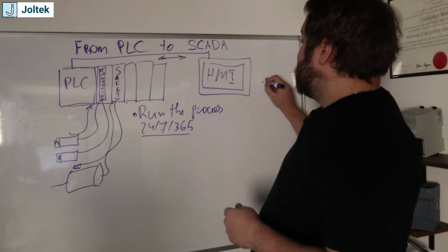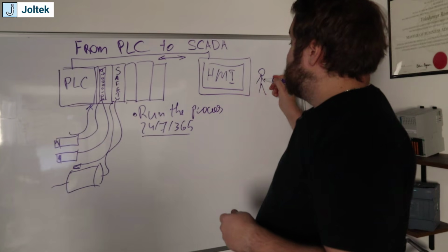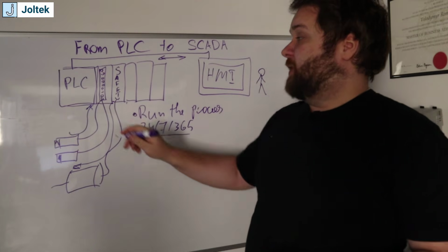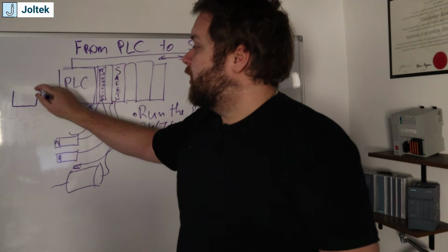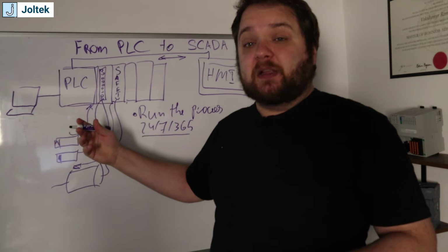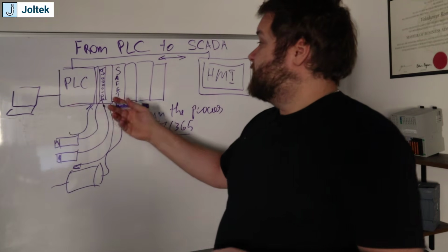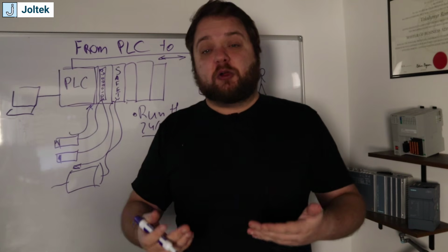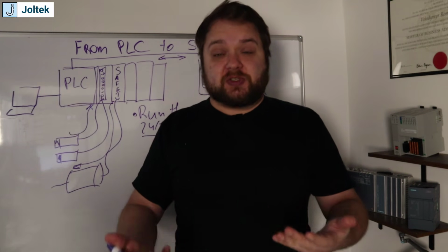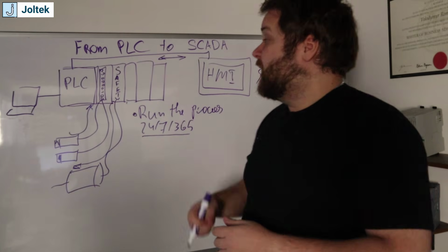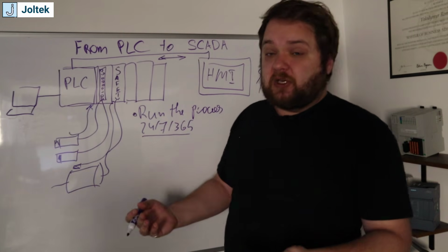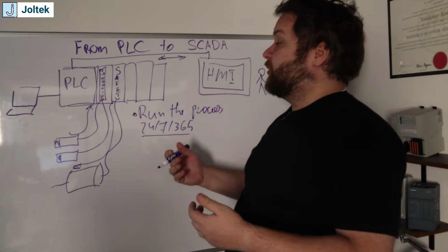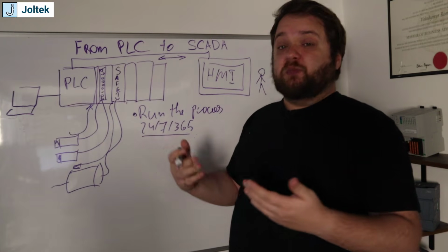But ultimately, the HMI is the interface between the operator and the PLC. Of course, the same can also be done via a programming terminal, right? So if you're an engineer working on PLCs, chances are you have a laptop that you can connect with, and you can make the exact same changes that an HMI would, but ultimately it facilitates how the operator uses the system, understands the system, troubleshoots the system, and basically works on the machine rather than trying to figure out the registers and the tags and some of the nomenclatures used inside of a PLC.